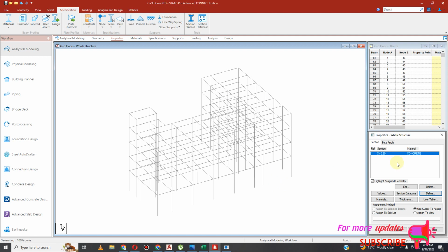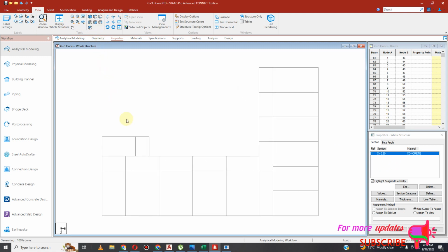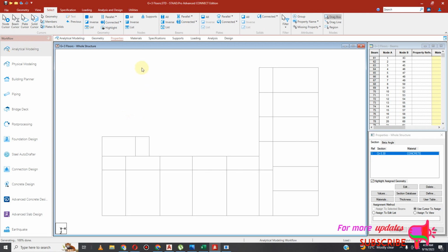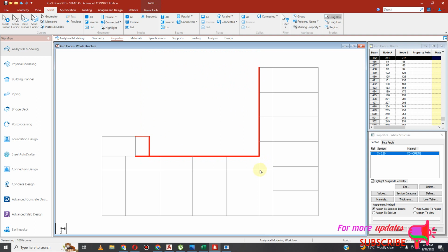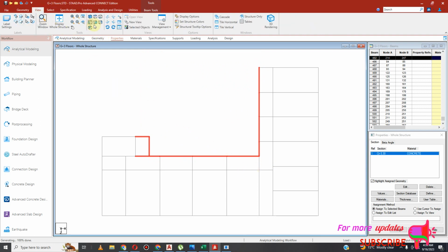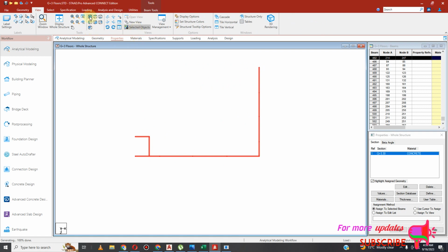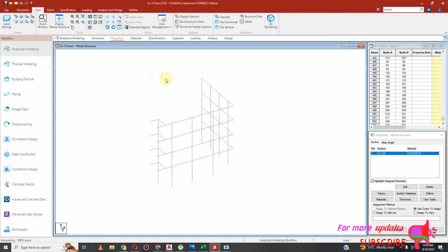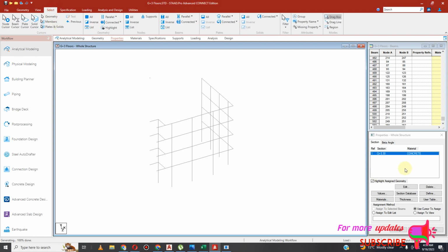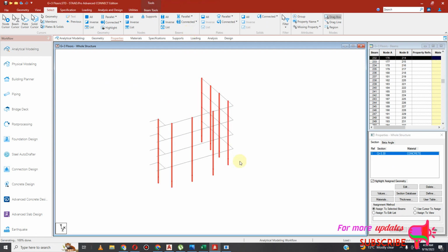And then I'll select all my circular columns. So I'll go to view. So I'll select that, the position of my circular columns, and then I will do selected image, then I'll go to 3D, then I will select units parallel to Y, then I will assign to the selector.